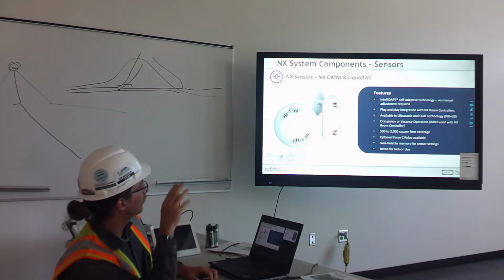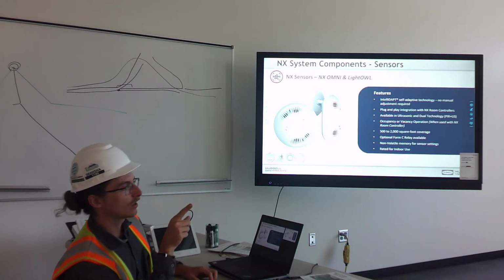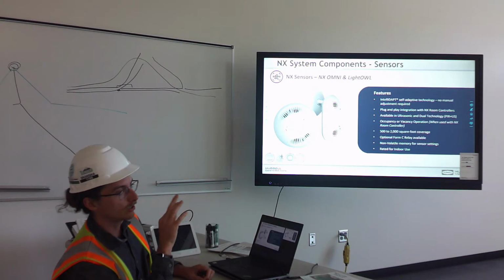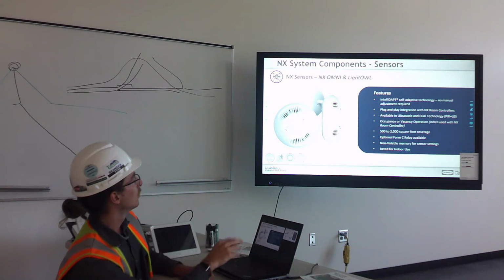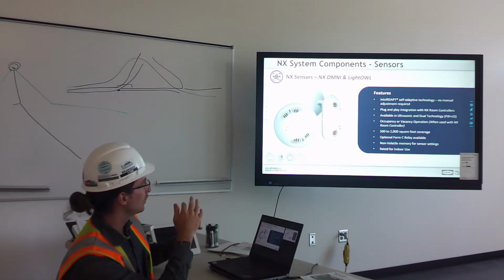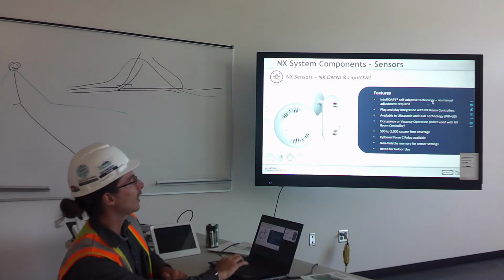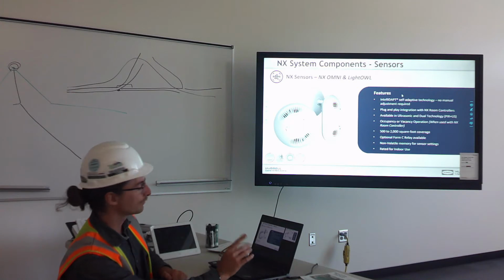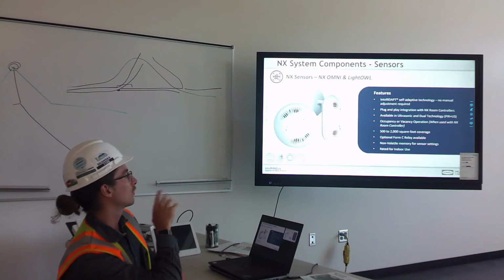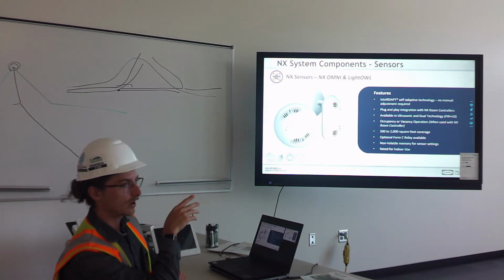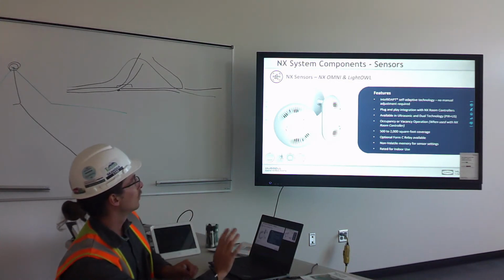Then there's another bank of B dip switches. B3 and B4, when you turn those on, allow you to adjust the time and sensitivity manually through the dials. Out of the box, those will be off, and they will be using what they call IntelliAdapt, self-adaptive time and sensitivity. Now, Prairie should be going through and setting them all to manual time for 20 minutes for the classrooms per the specifications. So that should be set up.